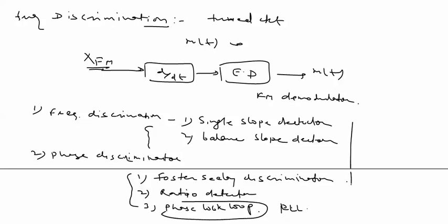This is the line which shows in this way it creates complexity to the system. Ratio detector is the best available method to us with accuracy, but it is a complex circuit. The highest accuracy is available with PLL only. Ratio detector is almost the best method for analog type of frequency demodulation purpose.